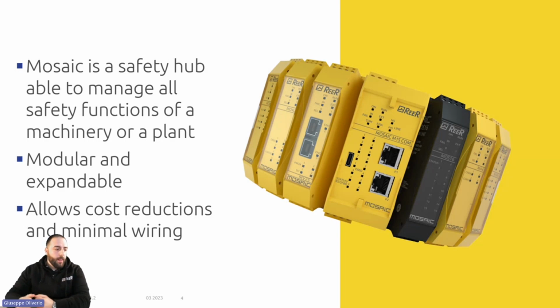Well, if you use a safety controller like ours, you will see that you don't need any safety relay, but you just need to connect the safety device directly to the safety controller and manage all the safety functions from the configuration software.